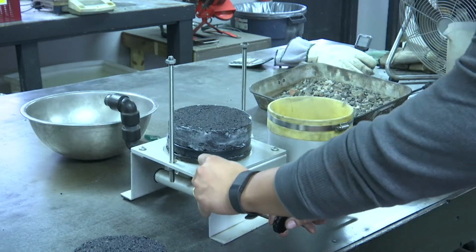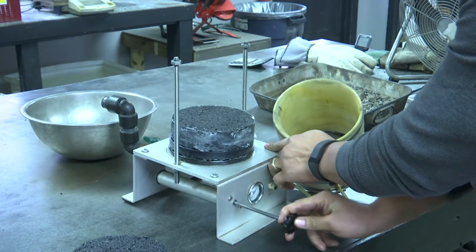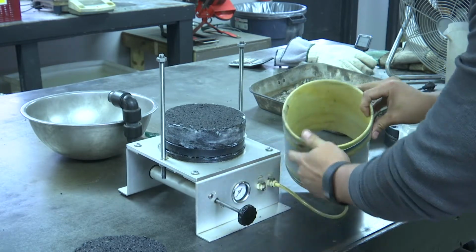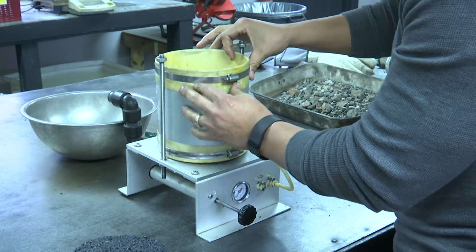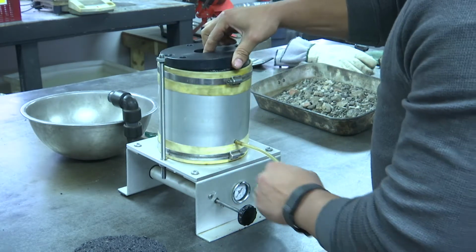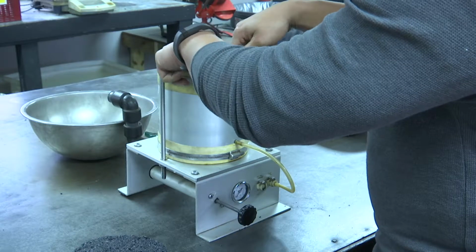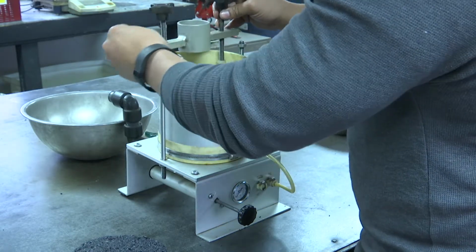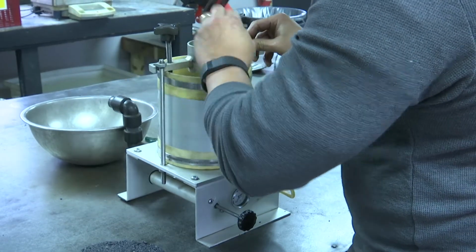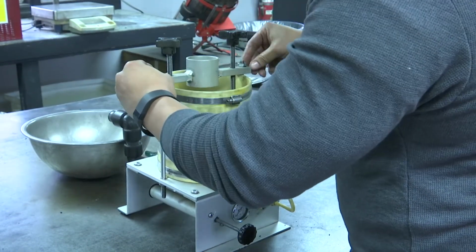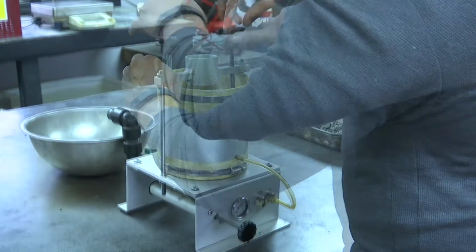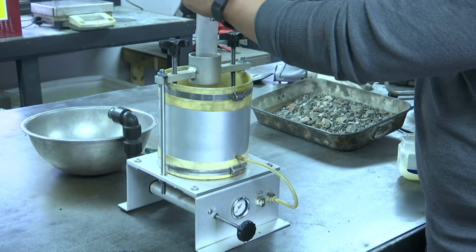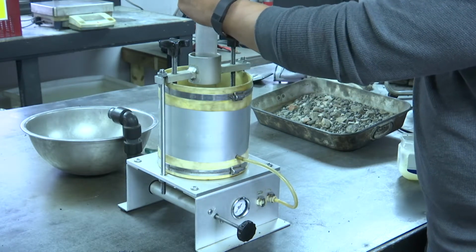Now what he's doing here is the vacuum that he's applying now is to make it so that the rubber membrane is pressed out against the sides of the collar. The collar is slid over top of the specimen. He's putting the top plate on his actual specimen, and he's going to bolt it into place and secure it nice and tight. Tighten it down. He's reinstalling his cylindrical tube.